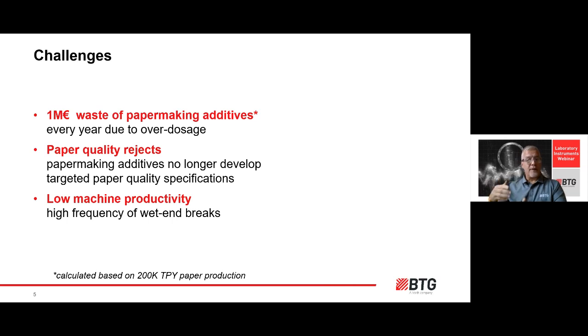Now, a little bit is good, and more is better kind of creeps into human nature. And sometimes we go even past that point of overdosing for quality because we think a little more might help a little more. In reality, it hurts. It can affect the paper quality negatively. You can run into issues with poor quality, and then you get into deposits. You can get into process problems like foam, and you can get into breaks, downtime, and rejected paper for those reasons.